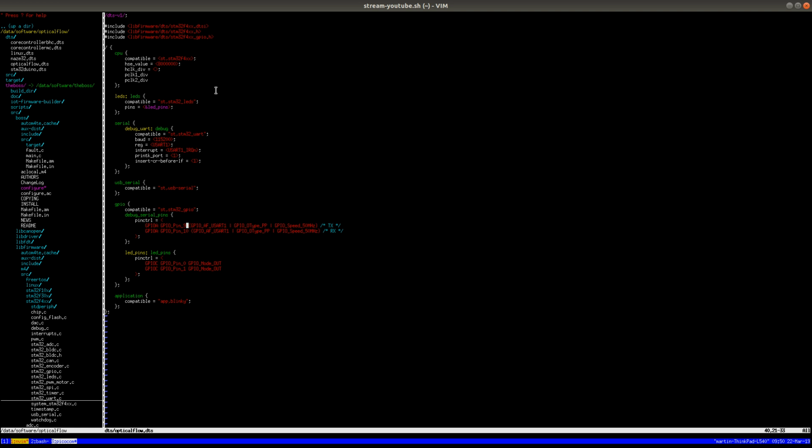One thing that is very simple with the device tree is configuring the GPIO pins. For example, for the serial line, I can easily remap UART1 to any other position where it's possible to remap this UART just by changing the device tree. I don't need to change any code, and I can have different device trees for different boards while keeping exactly the same code in the source code repository.